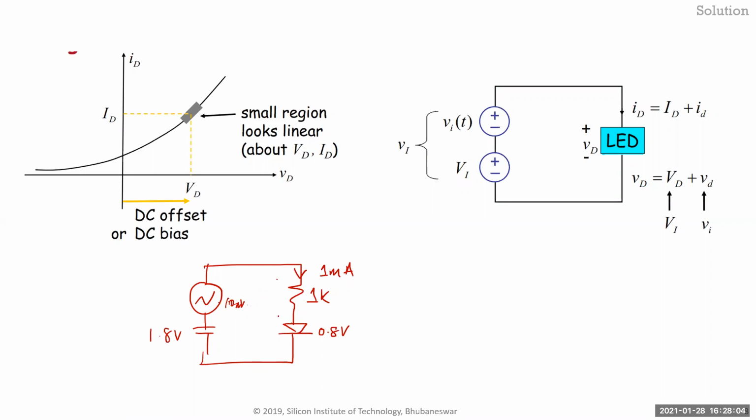by 1K. And I assume that for this small current, the VD is not varying much because it's exponential. So if you take the voltage, it's a log of that, right? So it's kind of compressed, right? So for a delta V of variation, your delta V in the diode is very small. So in other words, the current is almost linear.